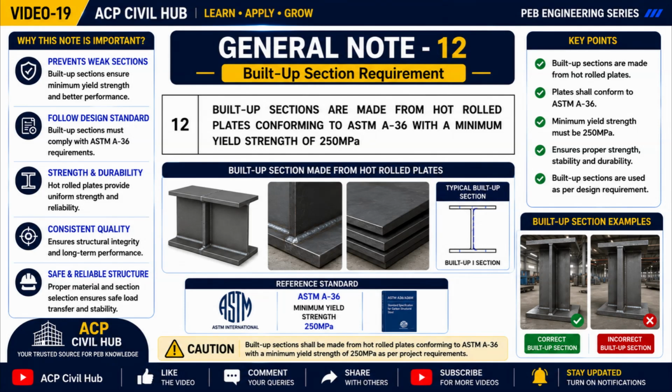During fabrication, engineers should verify that the steel plates supplied by the manufacturer comply with the specified ASTM grade before welding or assembly begins. Using the correct material grade improves structural strength, durability, and long-term performance while preventing failures caused by inferior steel quality. Always verify the material test certificates and project specifications before fabrication starts. This simple requirement plays a major role in maintaining the safety, reliability, and quality of every pre-engineered building project.